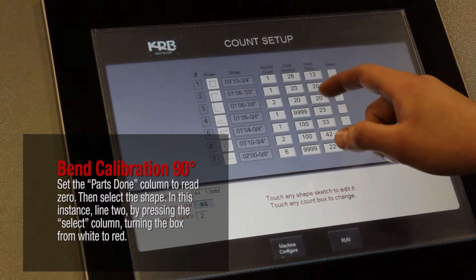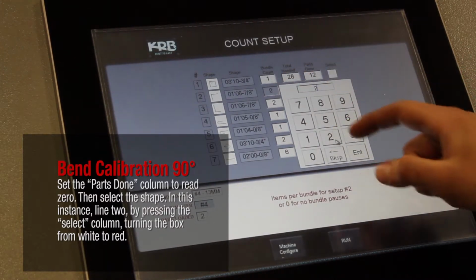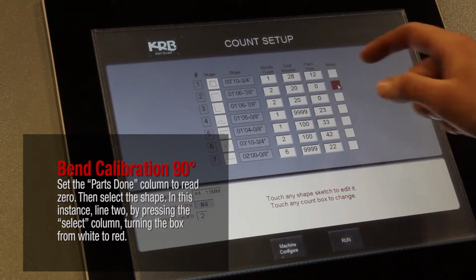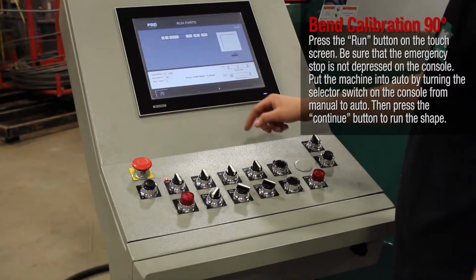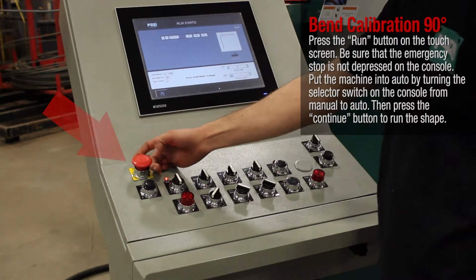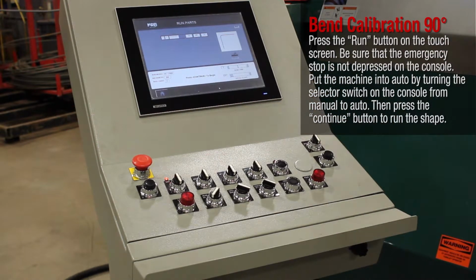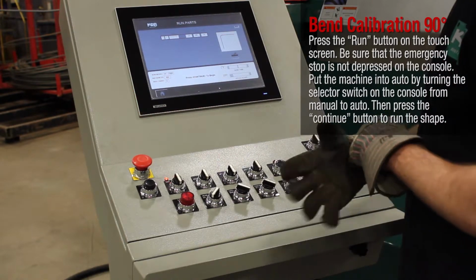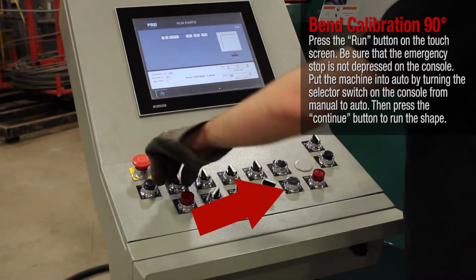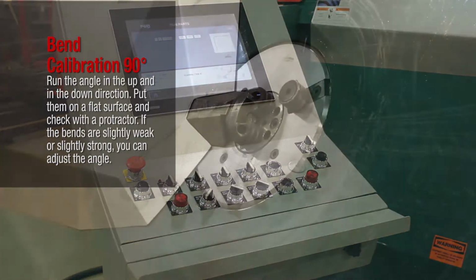Set the Parts Done column to read 0. Then select the shape, in this instance Line 2, by pressing the Select column, turning the box from white to red. Press the Run button on the touchscreen. Be sure that the emergency stop is not depressed on the console. Put the machine into auto by turning the selector switch on the console from manual to auto. Then press the Continue button to run the shape. Run the angle in the up and in the down direction.